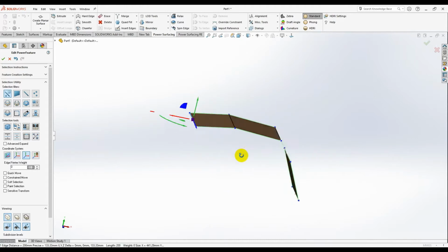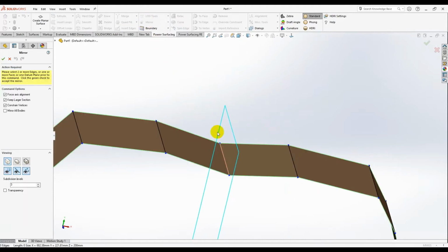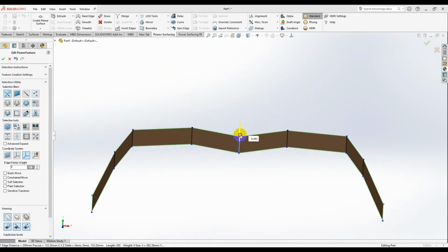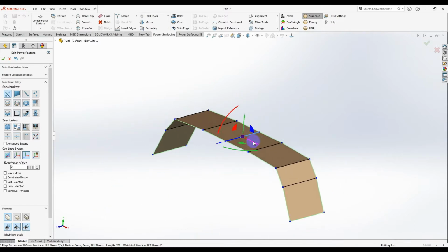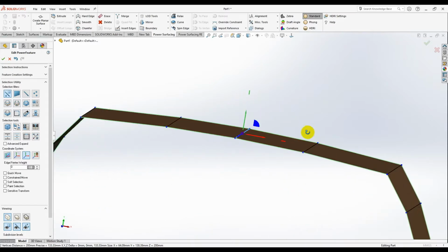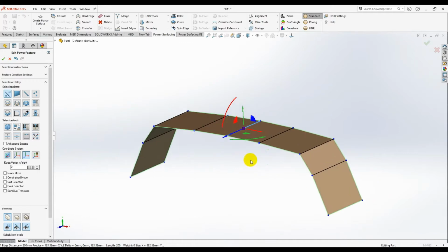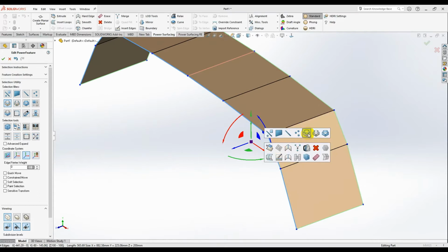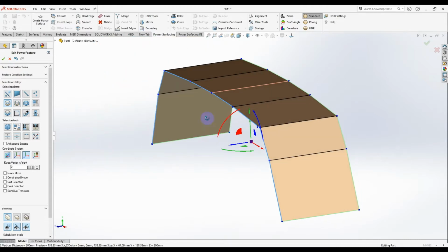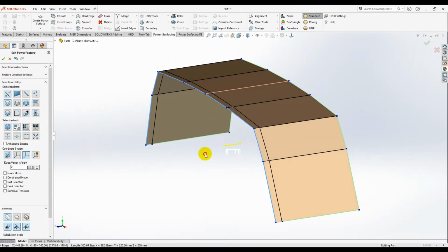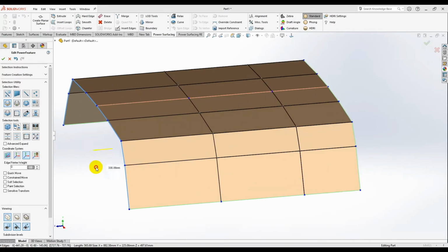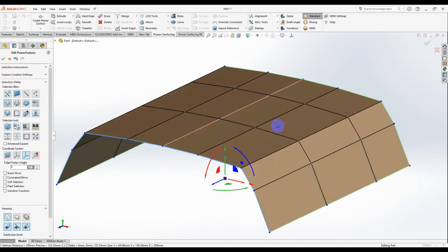Let's click from here and click on mirror. As you see, it's automatically mirrored, so I can easily move it up and down, and it's symmetrical. Okay, now from here I can easily select this whole loop by right clicking and clicking on switch to edge loop selection, and just snap by holding the A key. So I can make this like 3 times, as you see here.